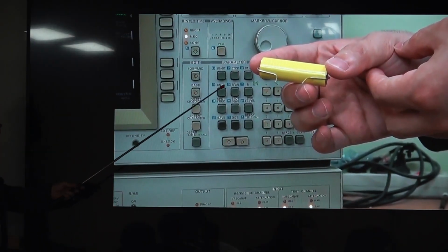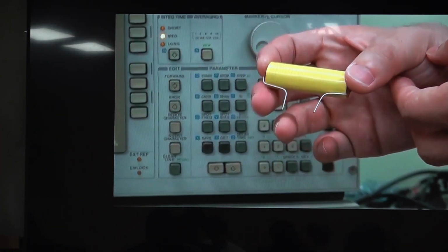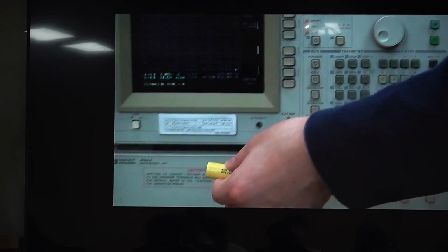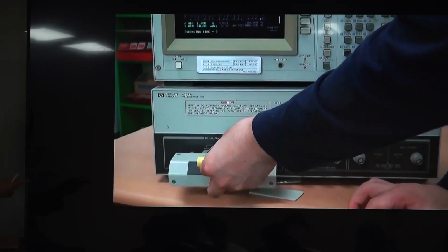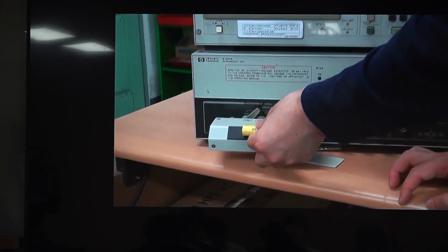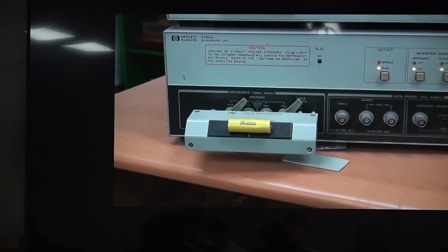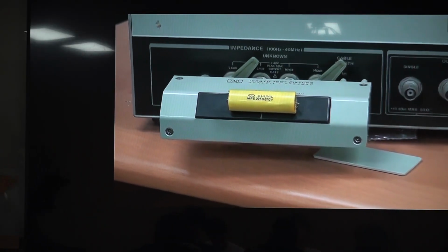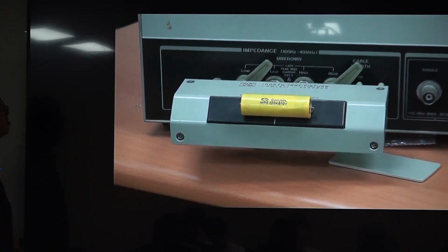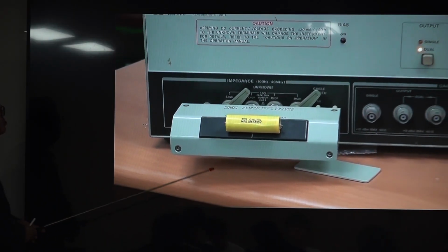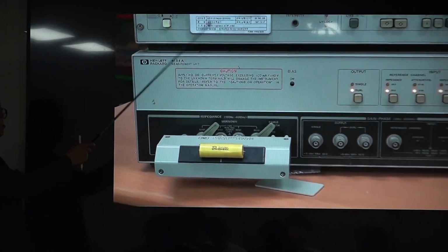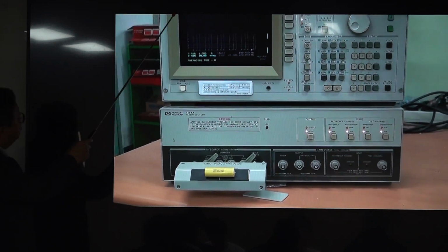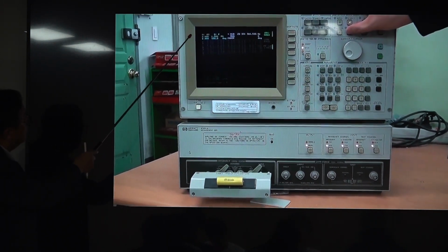And this is a capacitor, a film capacitor. This is big compared to its capacitance and voltage rating, so it has good performance as a high frequency capacitor. And I'm measuring this. Maybe this equipment stored some data, so maybe it plots very quickly now.